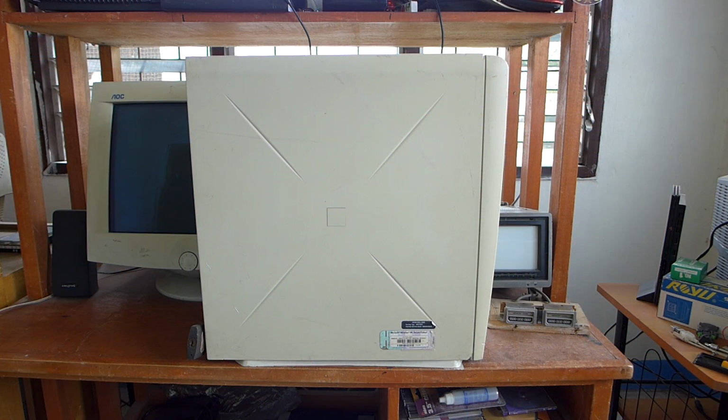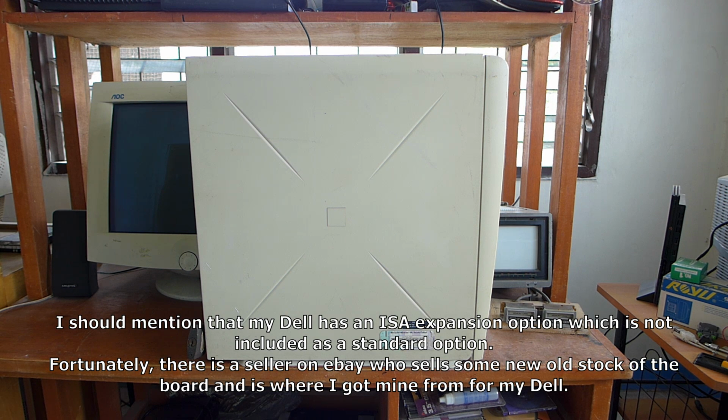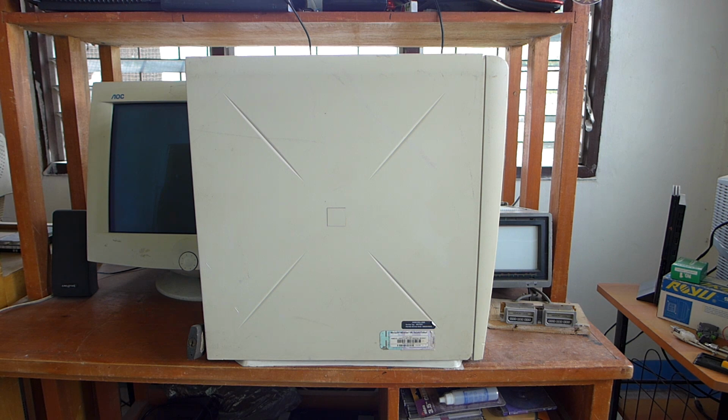In this video, the computer that I'll be using to install the DTL-H2000 boards to will be a Dell Optiplex GX110 computer. Any computer should be compatible with the DTL-H2000 boards as long as it has at least 2 ISA slots, and the BIOS has options for reserving interrupts for legacy ISA devices. I think you could still get away with installing the DTL-H2000 boards on a motherboard BIOS that doesn't have an option to reserve interrupts for legacy ISA, but it'll make things a lot easier if you have those options available.